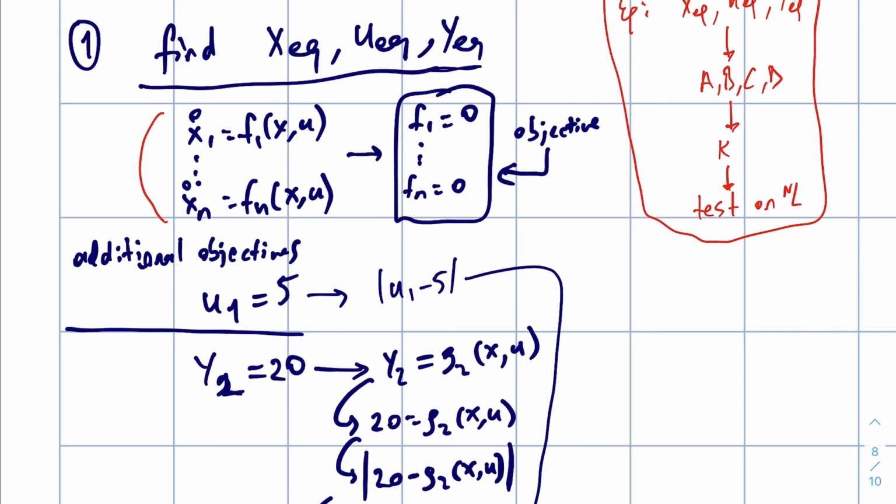Before moving on, I'd like to say a couple of side notes. You might like to have some constraints on your optimization problem. For example, for your planned nonlinear dynamical system, and it can be a real system, you have some expert knowledge about that, and there might be some specific reason for you to, for example, set one of your inputs to a specific point. Or maybe you like to constrain your input signals, like with inequality constraints. Maybe your motors cannot generate more than 5 Newtons, so you like to constrain that. This can be a reason.